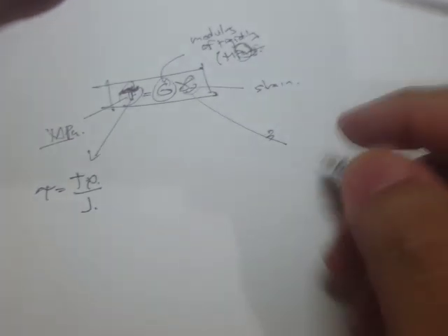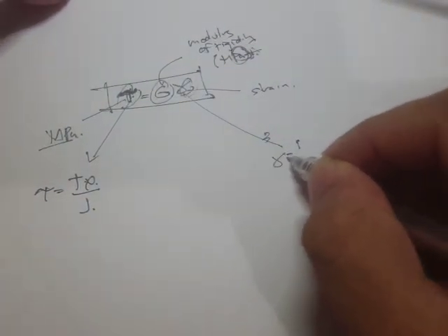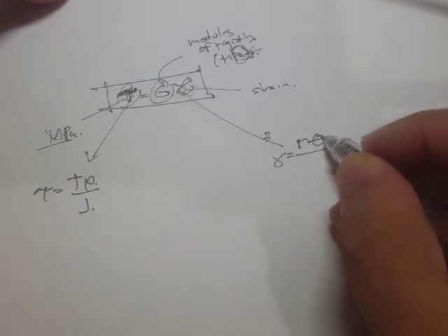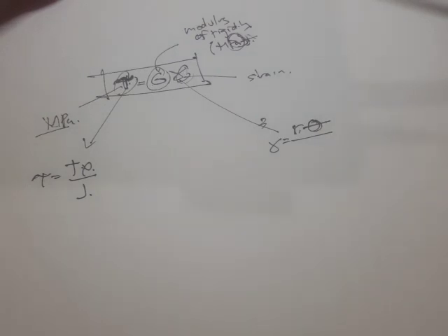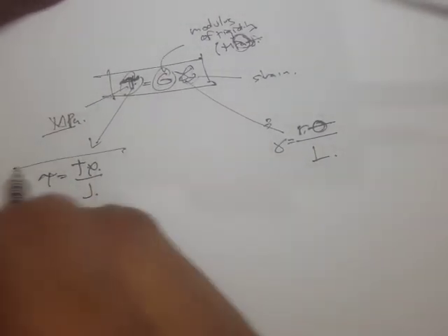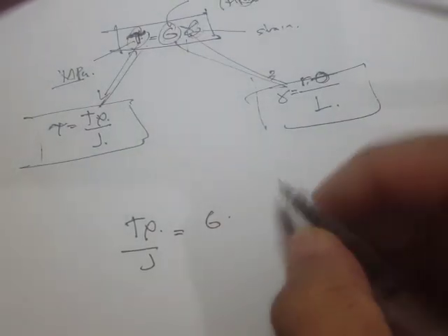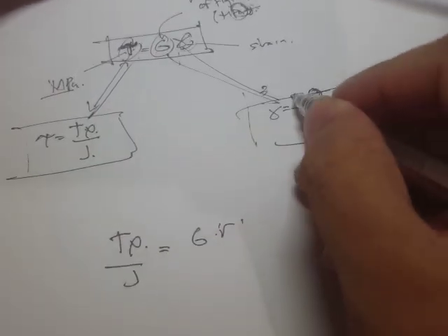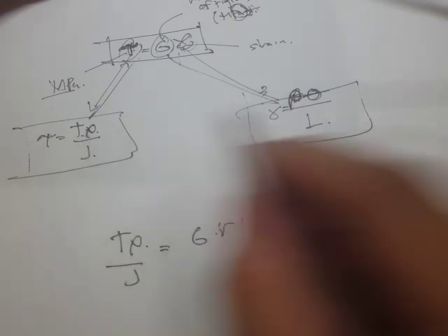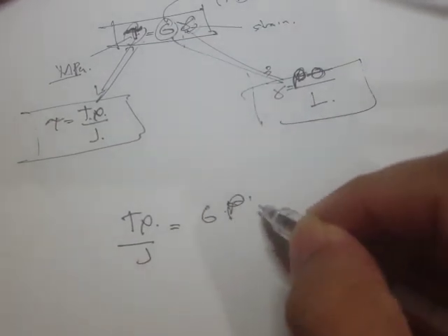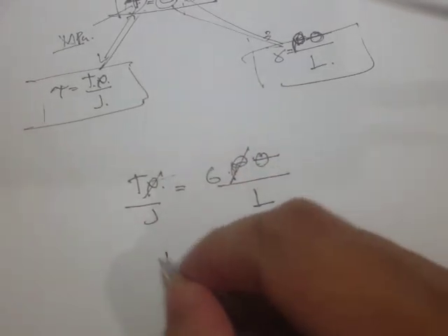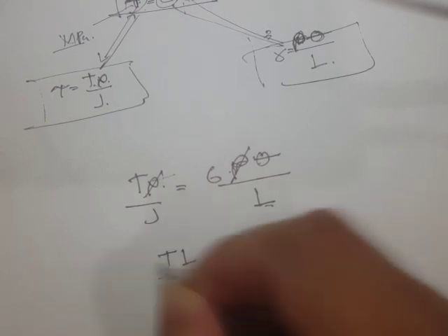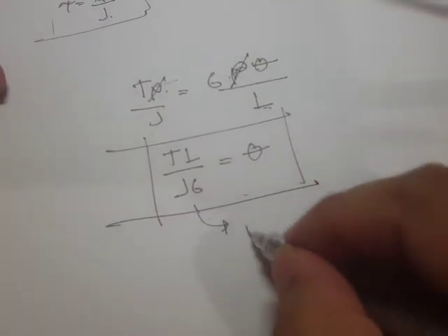And the shear strain is given by R times the angle of twist, R theta divided by L. If we substitute this into this equation, G times the shear strain, let's write rho to be consistent with this one, meaning that they are the same, theta divided by L. Since we have the same rho right here, what we get is theta equals TL all over JG.